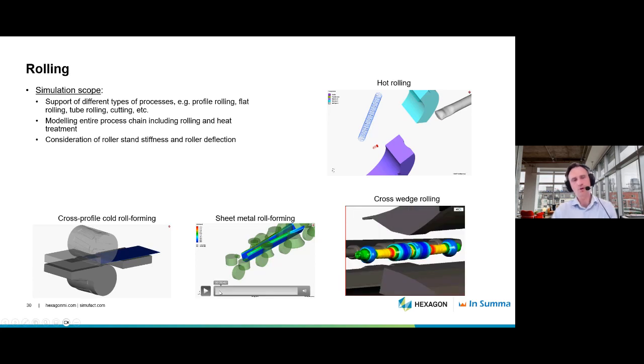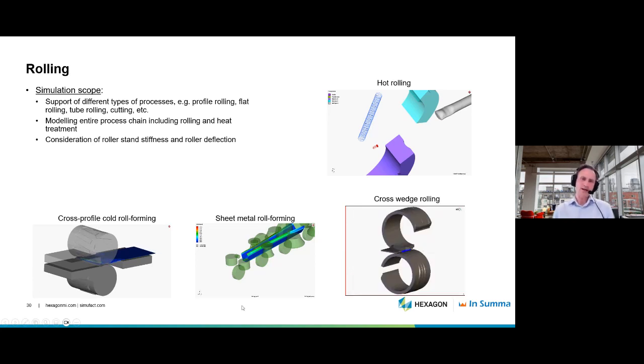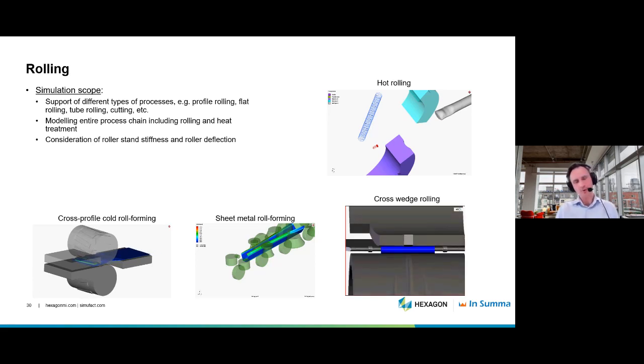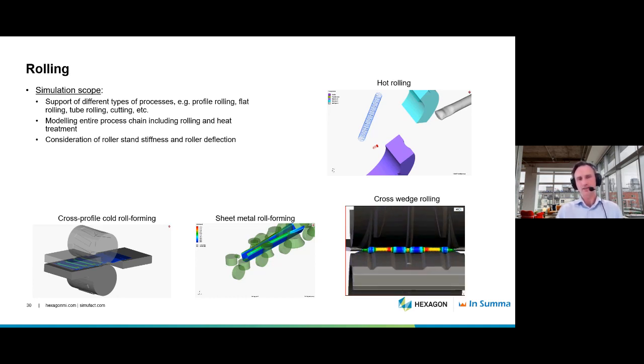where you have rollers which have some kind of special geometry. It's like a stamping process, but using rollers. So you have two rollers. One of them has the cavity, one of them has the embossment. They're obviously synchronized. So when you roll them, or when you pull the material through this set of rolls, you are forming these embossments on the flat sheet in a sequence.